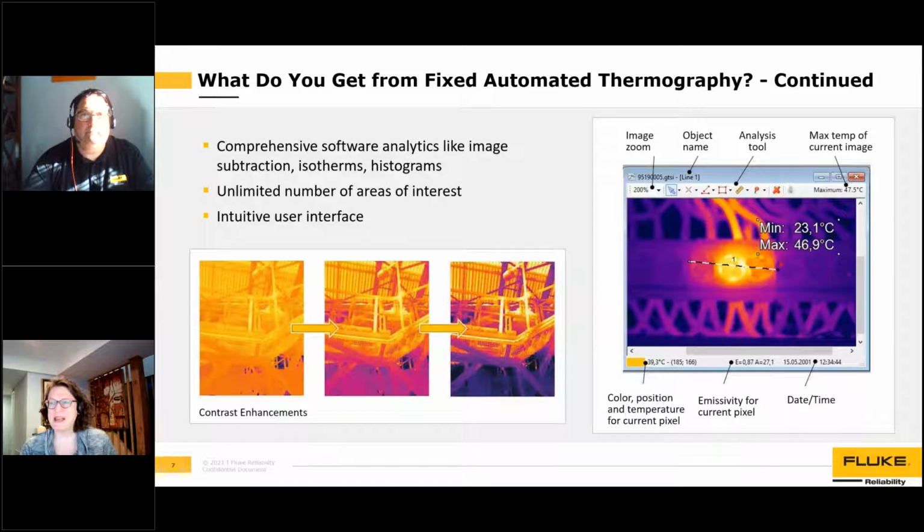Great. And one more. What are the gainful benefits between thermography or thermal monitoring and using thermocouples and other temperature sensors? So we do sell spot sensors, and the major advantage of a thermal imager versus say a spot sensor or even thermocouples is that I go back to what I said before, an image is worth 1,000 words. A thermocouple is going to be in contact with a specific area. However, it may not show you exactly where the root cause issue or the root of the heat transfer is coming from. It is definitely an indicator that there is some kind of change, and that can be true for a spot sensor. Spot sensors, however, only see what they are focused on.